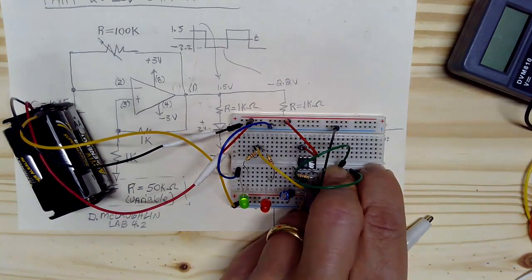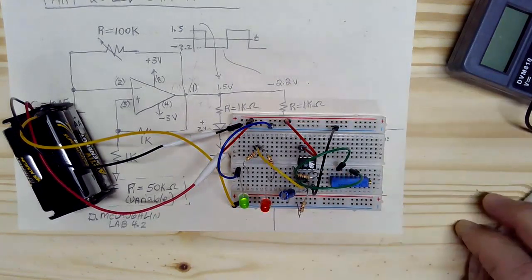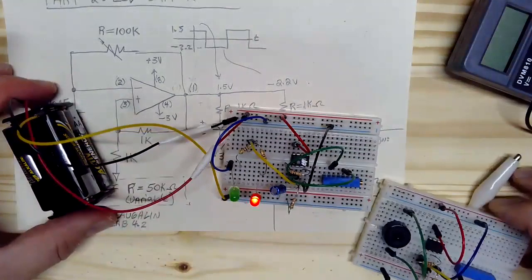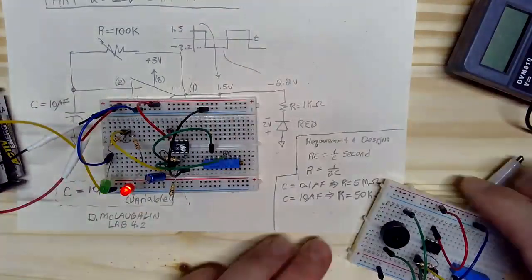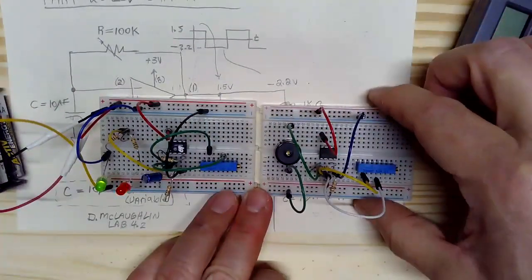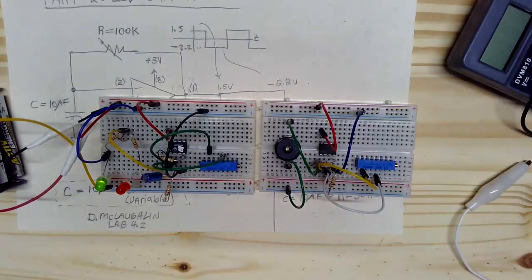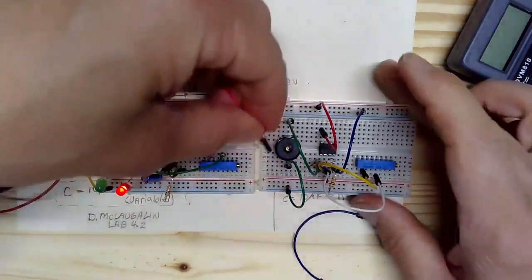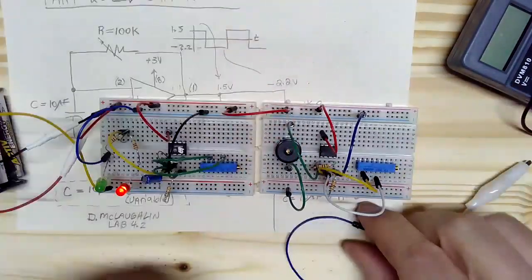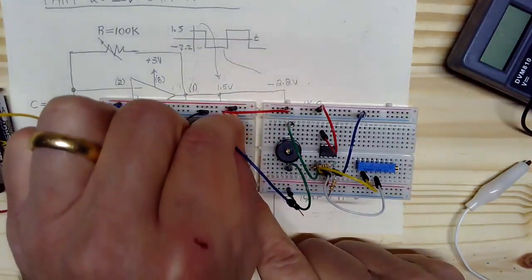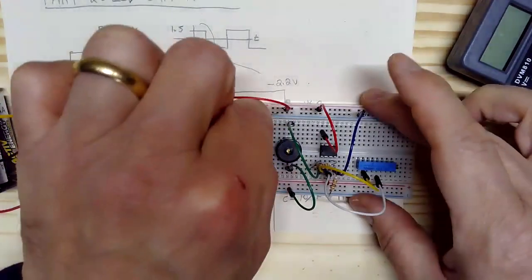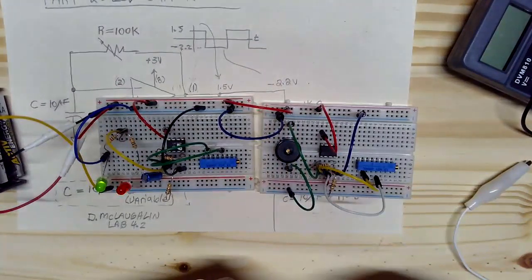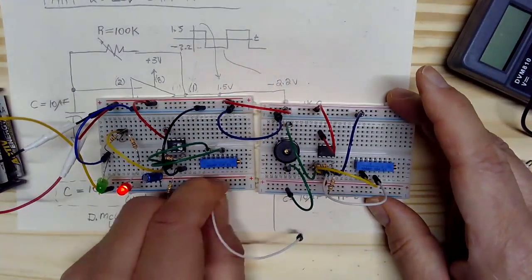half a hertz. Okay, so now I want to bring both of our boards together. And the way I'm going to do that is I've got my battery pack here. This one's all powered up, and I'm just going to connect the voltage rails and the ground between these. So I need to connect my 3-volt rail, I need to connect my -3-volt rail, and then I need to connect my ground rail. And when I do that, we should have blinking and singing at the same time.